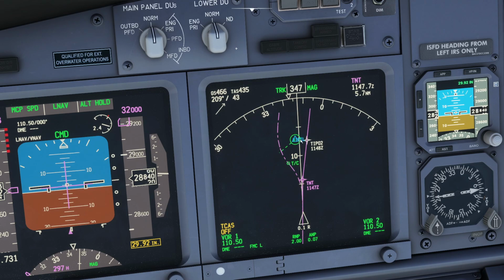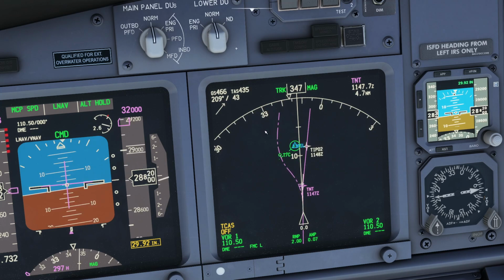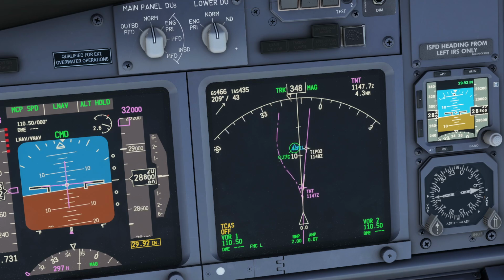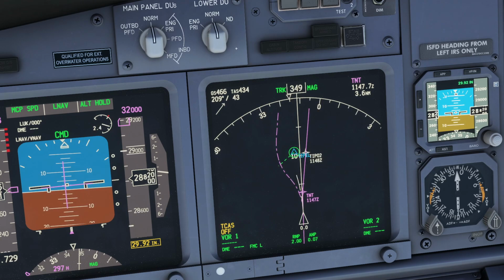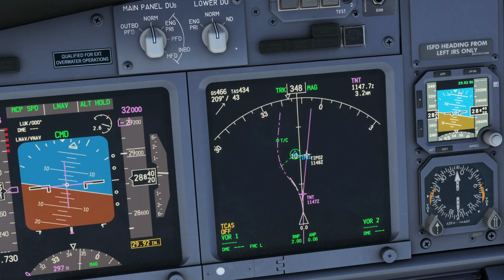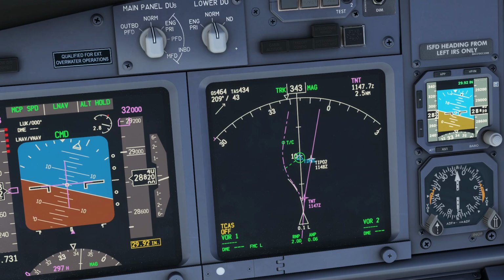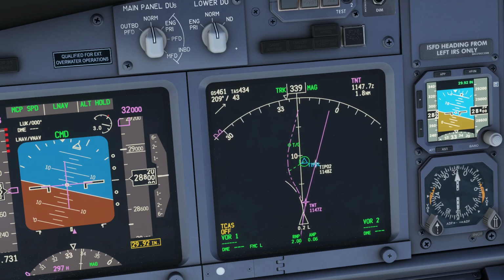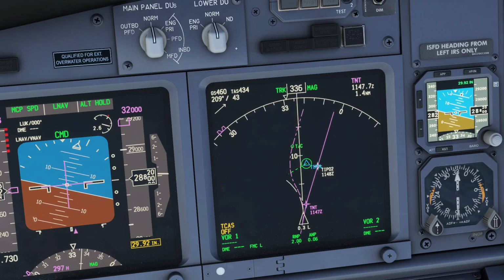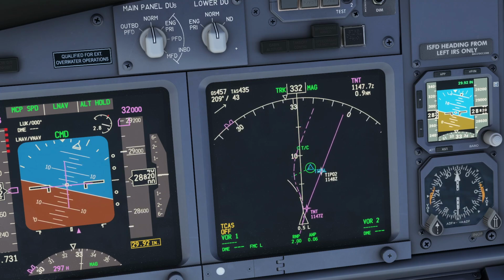So what's actually going on here is we've inserted a waypoint here, but it's offsetting 5 miles to the west of it, or to the left of it, sorry. So I guess the main reason you might use an offset is, if you are in a queue of other aircraft and you're closing in on an aircraft in front of you, you could offset by a few miles if it's a long range route without changing altitude. And just get out of the way of the ACARS warnings. So there you go, it's following it. It's very cool.